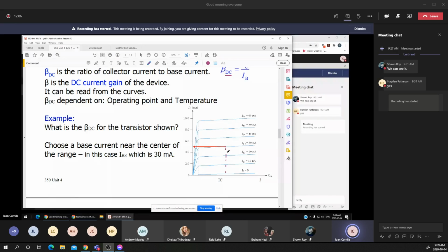You remember that I introduced the Q point or operating point with the diodes, because I use it intensively in BJTs. This point, the Q point of a transistor, is defined by the applied voltage and the external components, the external resistors placed around the transistor.